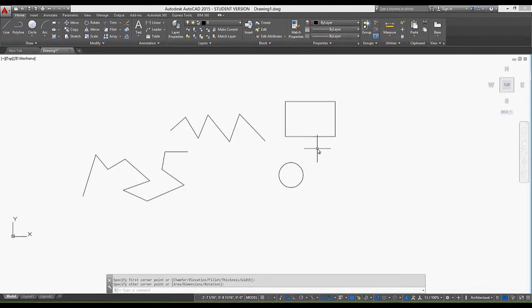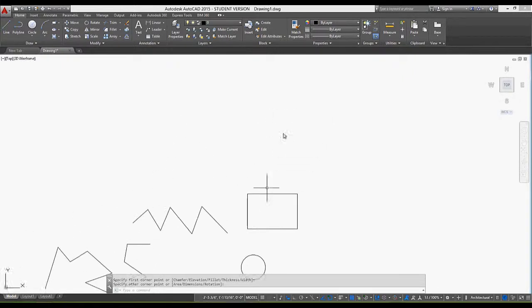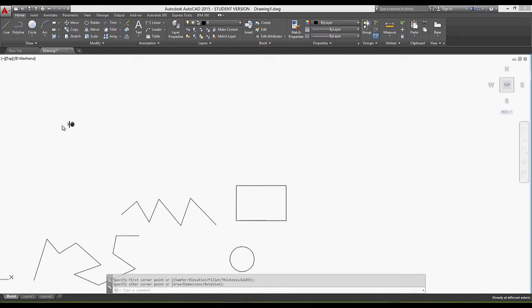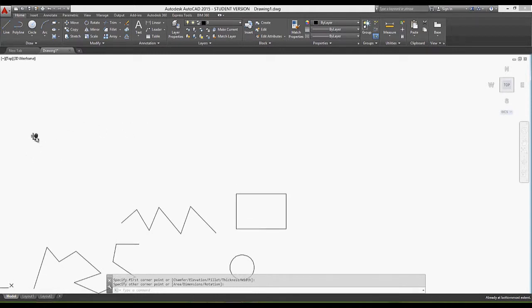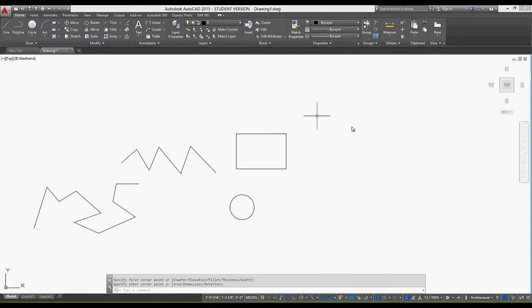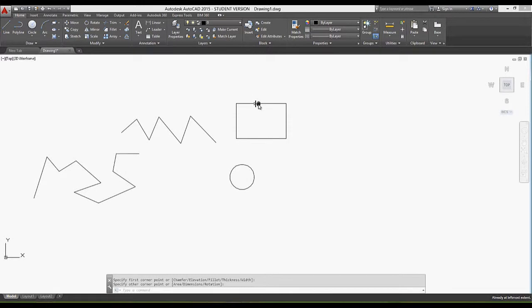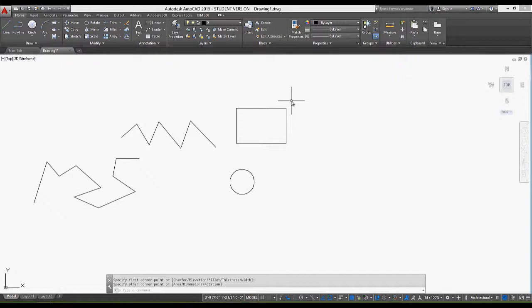Now, drawing limits. When I start to draft, and I start to move and pan, you'll see that if I get to a certain extent, what happens to my pan hand is that now there's this edge to it and these arrows. And that's essentially the drawing limits that AutoCAD places on your drawing file, your model space. It's basically saying, just to save memory or whatever, I'm going to keep it confined to a certain area, and if you ever need to break the area, there's ways of doing it.